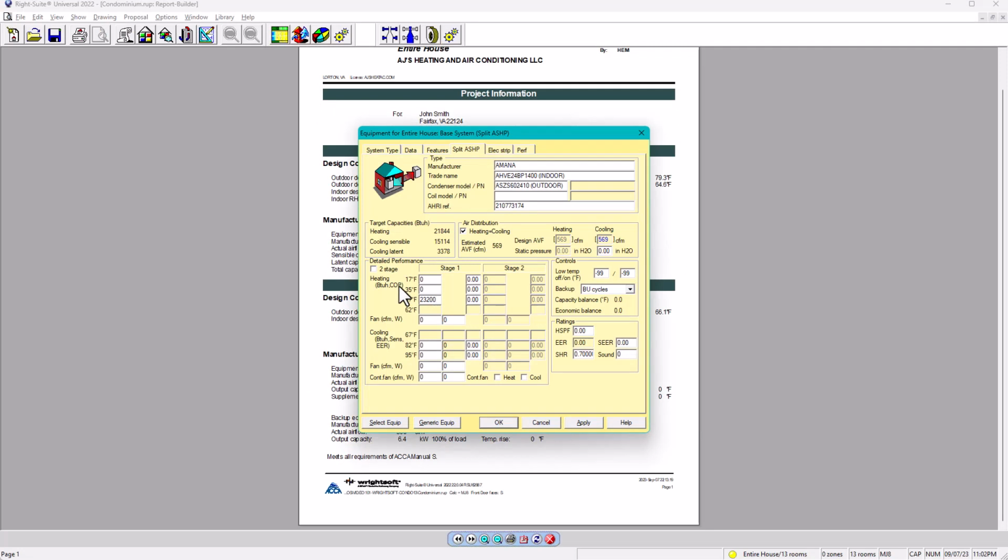That's for heating from the heat pump; auxiliary heating is different. Now we're going to go for the cooling. This cooling is very interesting. Do you remember the AHRI conditions? The capacity depends on conditions, either design conditions, AHRI conditions or ACA conditions. In this case, we took the capacity for AHRI conditions, which is at 95 degrees Fahrenheit. So at 95 degrees, what is my capacity? In here it says BTUs per hour and then it says sensible.